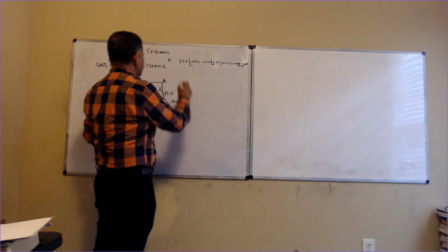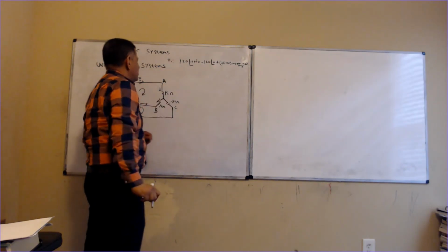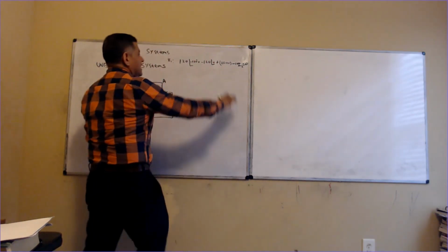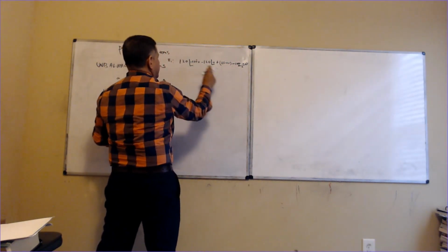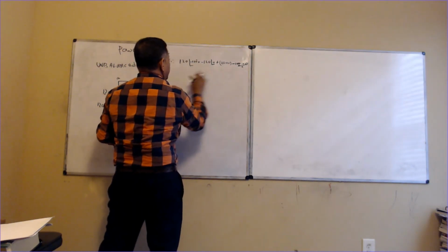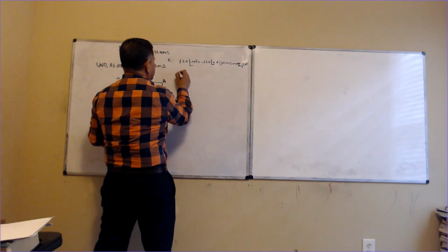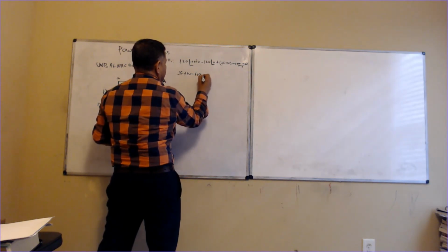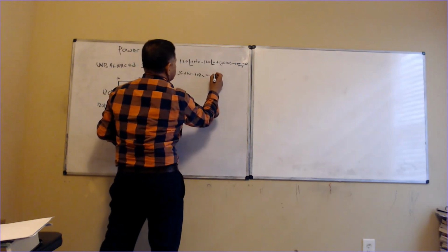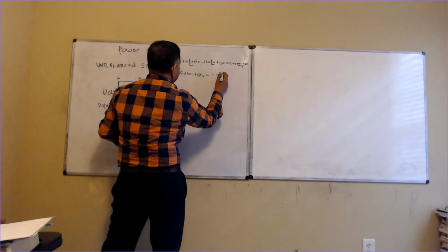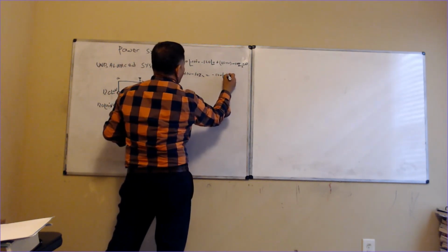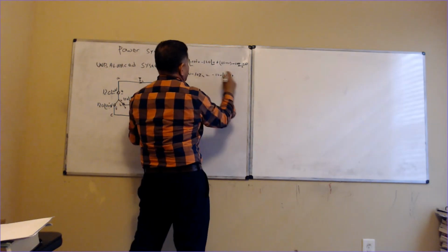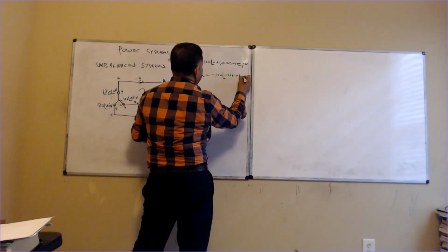Simplifying, I can leave only this on one side and subtract the source to the other side, and I get (10 plus j5) I1 minus 10 I2 equals minus 120 volts at angle minus 120 degrees, and then plus, so I am adding 120 at angle 0 degrees.